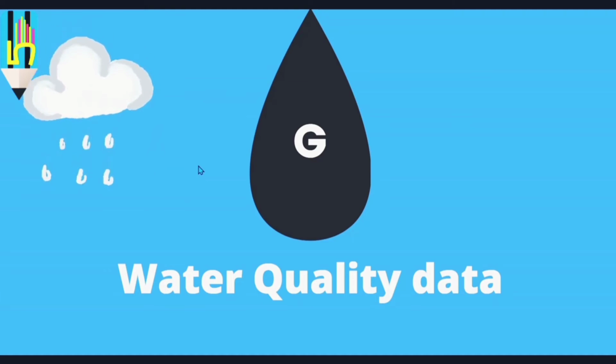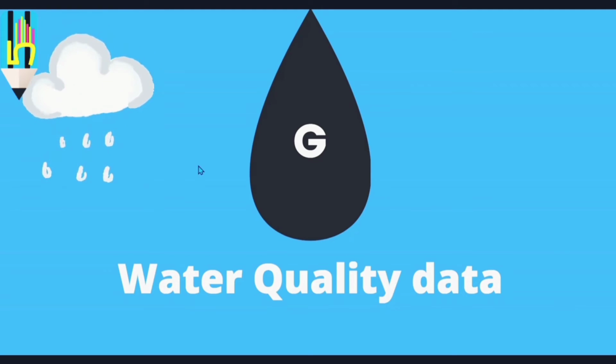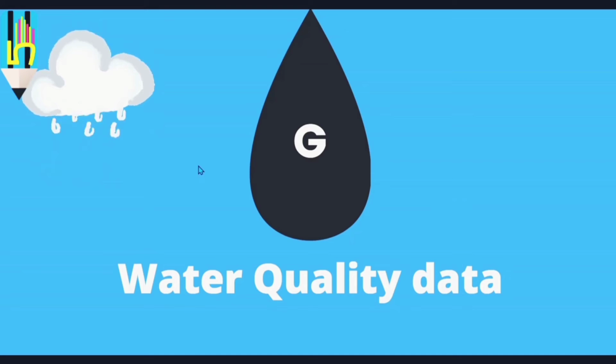It is for the simple reason that if you are living in a place which is full of groundwater, when you extract groundwater, it needs very little treatment. But how much treatment it needs, we need to know, na? So for that we want the water quality data. With water quality data, it checks all the parameters which we have read, like the pH, turbidity, chlorine, etc.